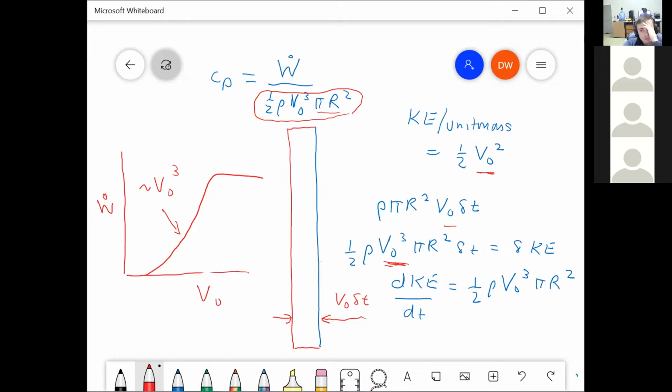If you go to any wind turbine manufacturer's website, you should be able to download the numerical data for a power curve, or you can get it from the database in SAM, and do a bit of power law fitting. If you do a power law fit for this region of the power curve, roughly 5 to 10 meters per second, you will find that it's an approximately cubic dependence. So these are very simple considerations, but they give you a lot of information about how wind turbines behave in terms of the form of the power curve for that range of wind speeds.